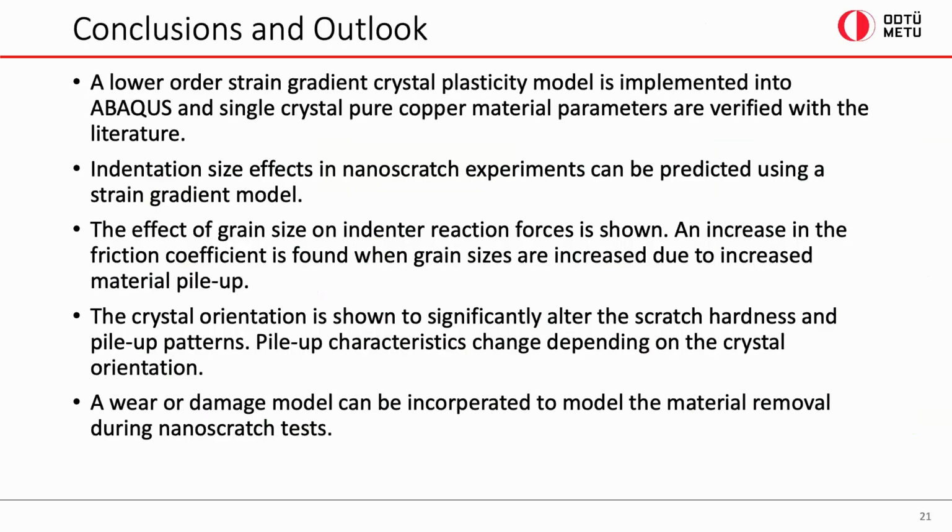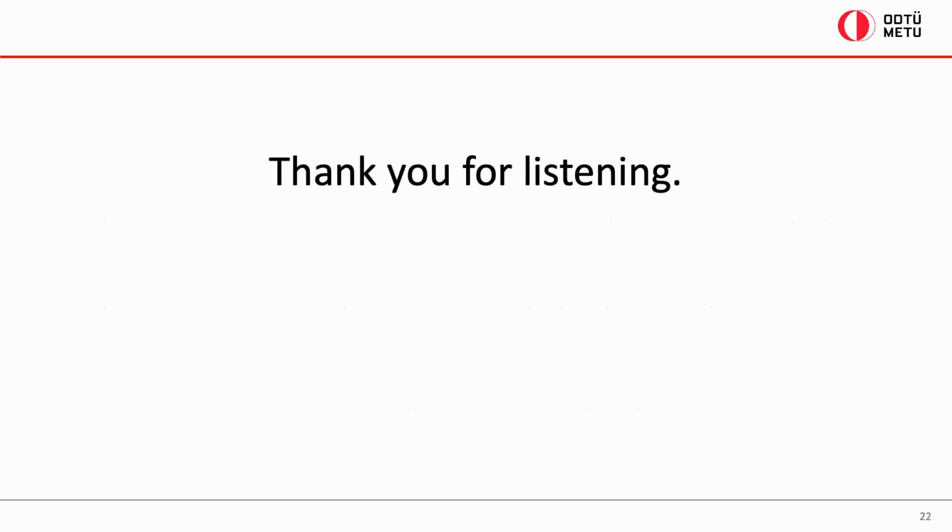And finally, in our conclusion, we've seen that indentation size effect can be modeled using finite element methods, the same as the grain size effects, and the crystal orientations show a significant effect on material pileup. And finally, by including a wear or damage model, we can also compute the chip removal or material removal during the nanoscratch processes.